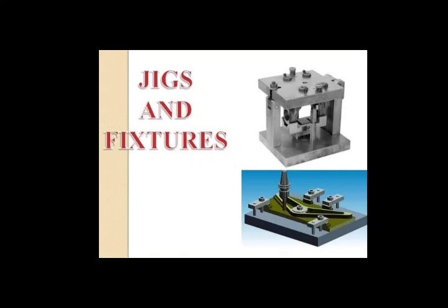Rigidity. Jigs and fixtures must be strong enough to withstand the various forces produced in machining operations. And last but not the least, an important point, safety. Jigs and fixtures should be designed for safety. Another point that is commonly asked in the exam is wear resistance. So, what is it? As jigs and fixtures are used in mass production, a considerable amount of wear may be observed, which affects the accuracy. To eliminate this, suitable hardening techniques can be used to increase the wear resistance of the devices. You agree with this? We'll go forward again.